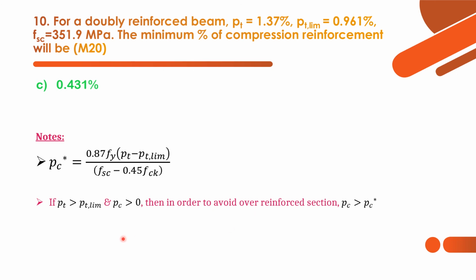So we have seen all the formulas of moments of resistance, and how to calculate neutral axis in case of other stress block diagrams, and how to follow IS 456, what is the xu limit value. Accordingly, we have to calculate the fy and fe values. So we have seen some of the most important things in case of limit state method that we can expect in the examinations.